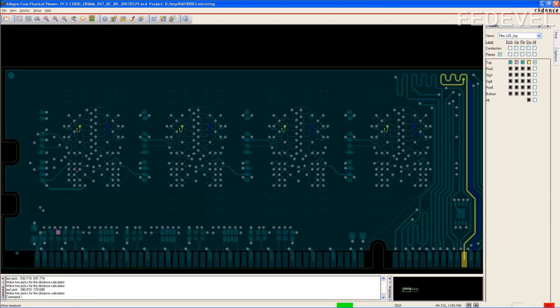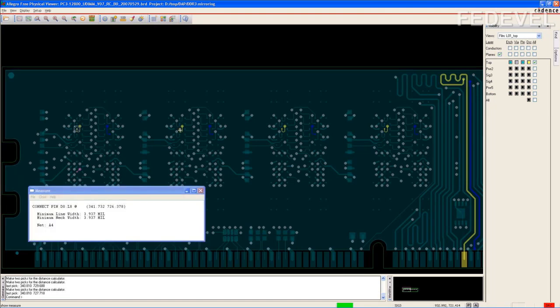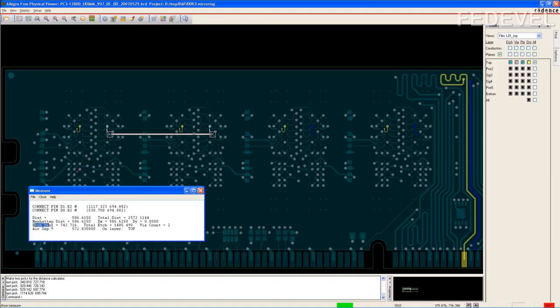And then I also measured the distance between these two memory chips. So I measured what is the distance between yellow path from here to here, that was the 742, and what is the distance between blue path from here to here. That's the distance between these two memories, 742. You see the distance is exactly the same. We are looking for this edge distance. This edge distance, it means it's the copper distance. It's the distance of the connection, copper connection between these two paths.